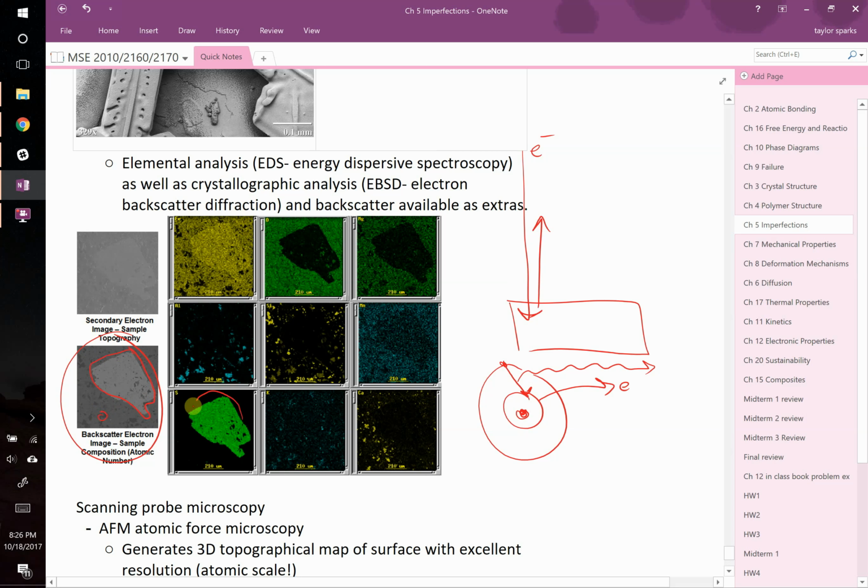And then when you couple this with EDS, you can now see right away that, okay, this region right here, that's sulfur. You can see other things that, let's see, that also had iron in it. Looks like it was rich with iron and sulfur, so it's probably some iron pyrite. Whereas the rest of it, this is magnesium out here. Looks like it's oxygen, a little bit of manganese. So it's a really useful tool for figuring out what is there. So if you had a material that failed for some reason, you can do some really interesting diagnostic work to figure out why it failed and what were the sort of impurities that were there.